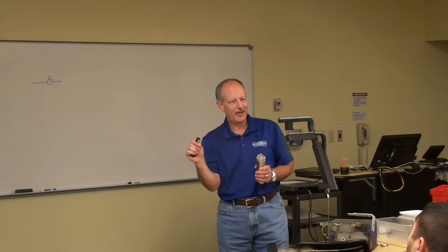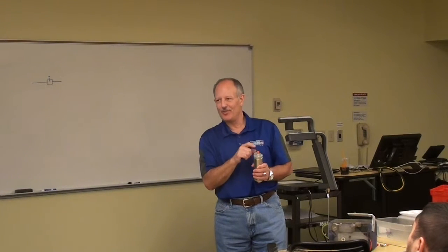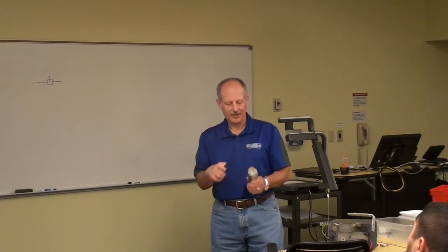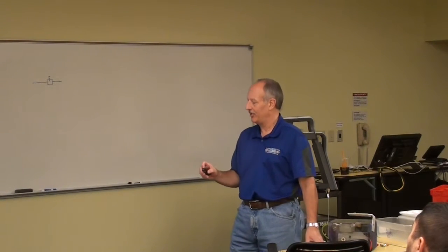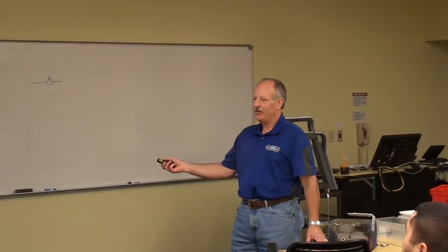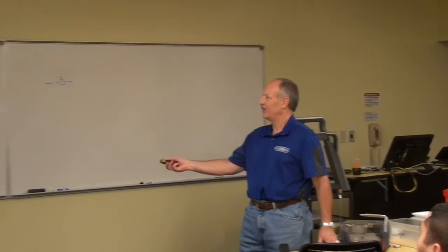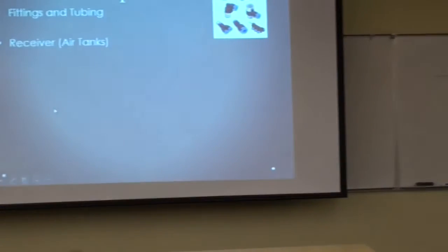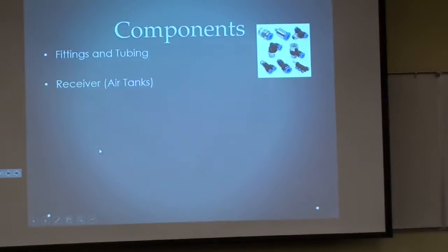And sometimes you get millimeter spec tubing. You have to use it with millimeter spec fittings. If you don't, they're going to leak. They may fit, but they'll still leak. And believe me, you do not want to chase air leaks. They're a pain. Soapy water. Soapy water, that's correct.